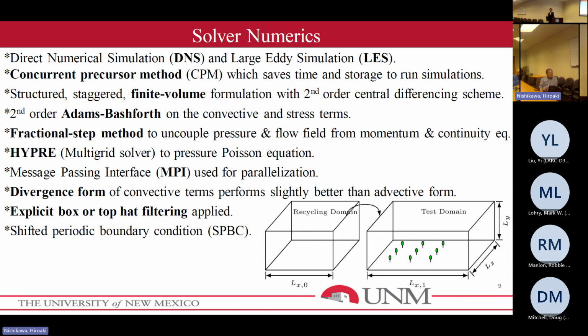So basically, a low surface roughness is better. If you have a higher surface roughness, it sometimes makes the wake recovery more complex to analyze. Before you build a wind farm, you need to do some kind of calculation. If you have a smoother surface, you can predict how much energy we can generate over 20 or 30 years.